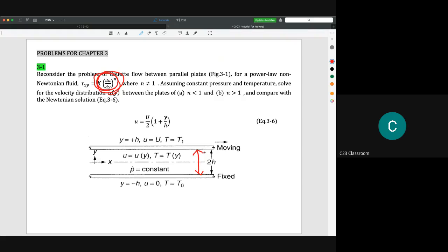As you know, the shear stress is equal to mu du dy. So the shear stress will increase if the u is increased. The velocity here is the prime influencer, the main parameter. But what happens if the y increases, and let's say the u is constant?